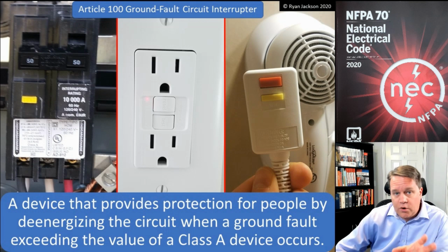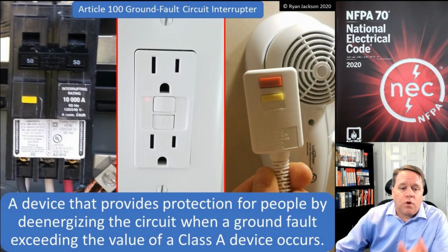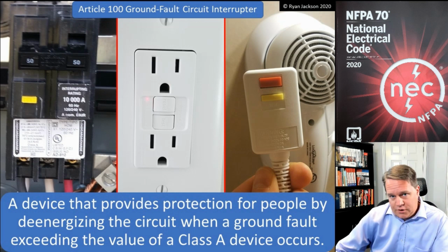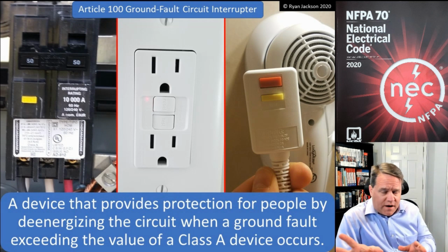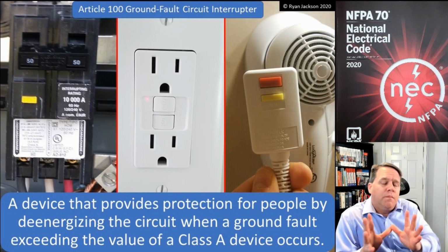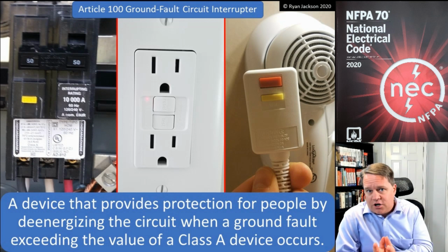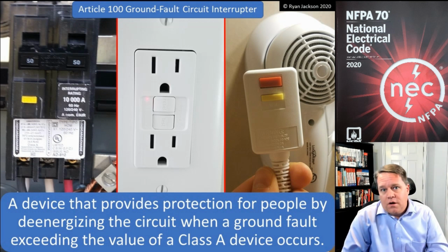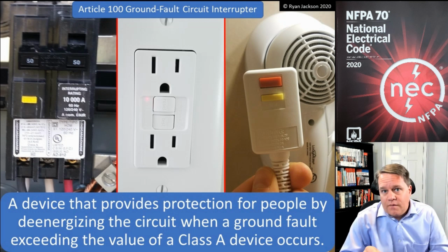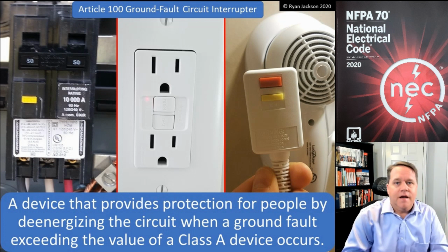Now, it's important to note a few things in the definition. First of all, when we talk about GFCI protection, we're talking about protecting people. And we're talking about Class A devices. We're going to find out in just a second what that means. But suffice it to say that if the code requires GFCI protection, it has to be a Class A device, because that's the definition. The only type of GFCI that meets the definition of a GFCI is a Class A GFCI.